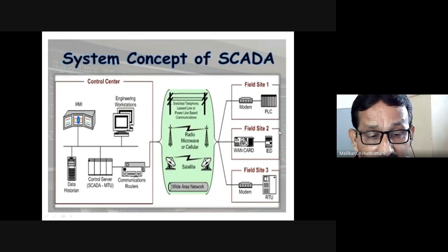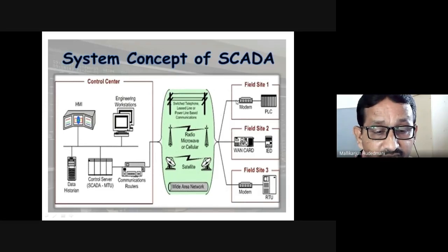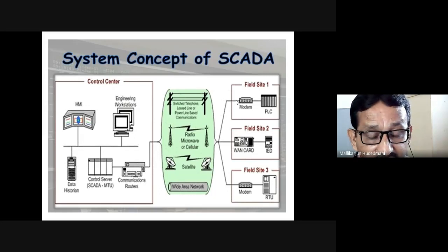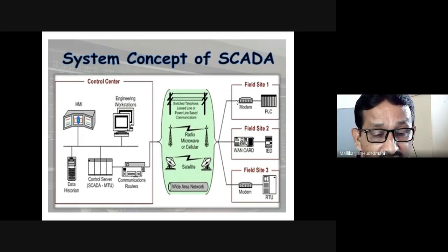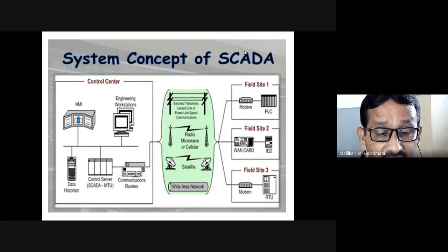This is the area like 1, 2, 3, which we call RTU, remote terminal unit, which is composed of a PLC, a computer, computing facilities, which will collect all the necessary information for the processing to be taken at the energy control center from the perspective of that locality, maybe a generating station, maybe a load center, etc. That information, after being encoded, is telemetered to the energy control center. So these transmission representation lines are nothing but communication sections.